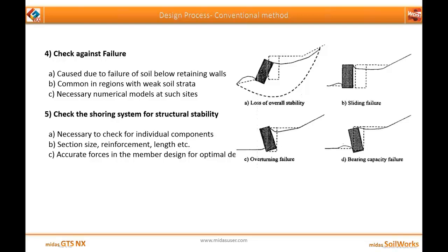Also, one needs to check the shoring system for structural stability. For this, one should know the accurate forces which are coming in the members for their optimal design, for the section size, reinforcement and length to be considered. So in such situations, numerical modeling becomes very, very important.